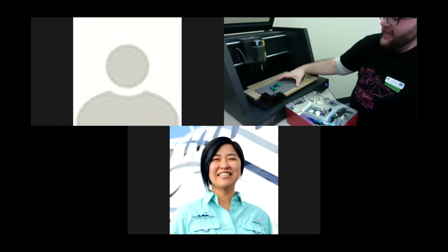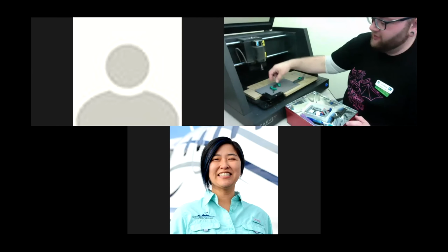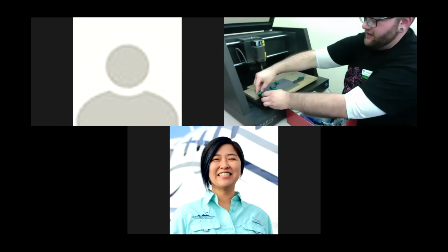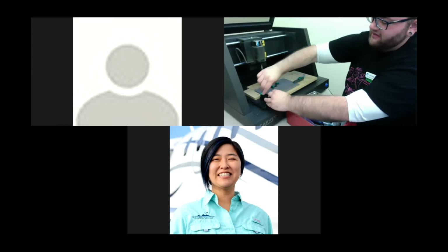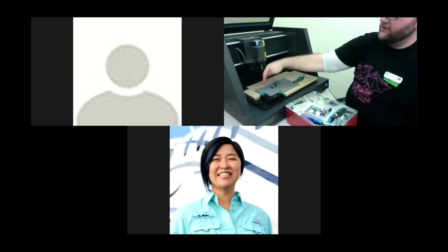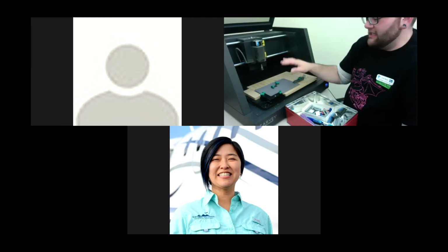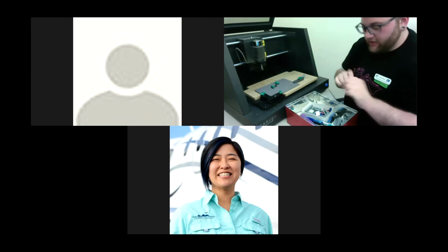So I did the edge first, just in my excitement to show it to you, but you really want to do the smart clamp first. The smart clamp already has pre-drilled holes. So once you get it kind of seated here, you can do the one over here, and then we can do the one over here. And then once that's in there, you can go around and do the others. I only put them barely finger tight at first. You don't want to tighten them all the way down until you get them all in, kind of like with a car tire. You want to do a star pattern to make sure it's equally torqued.